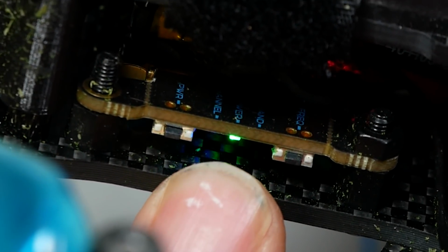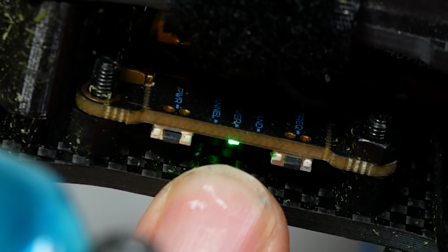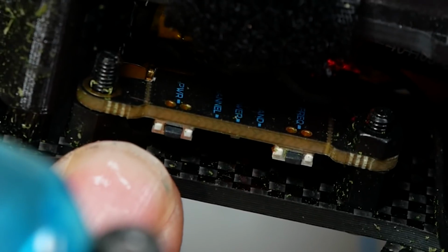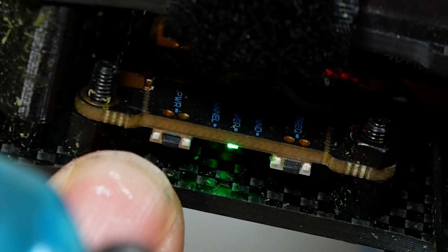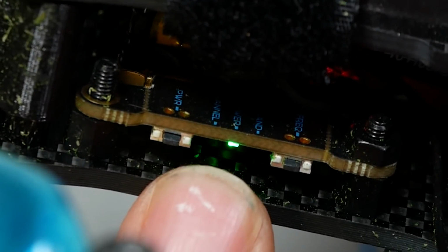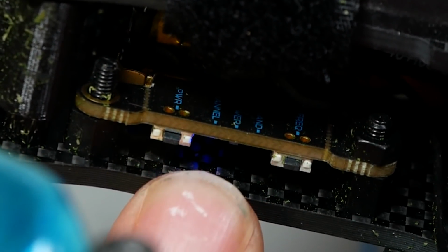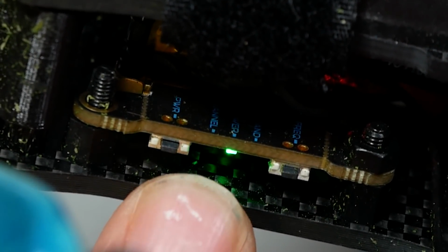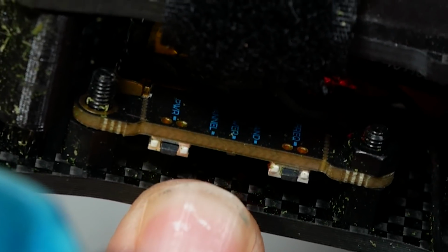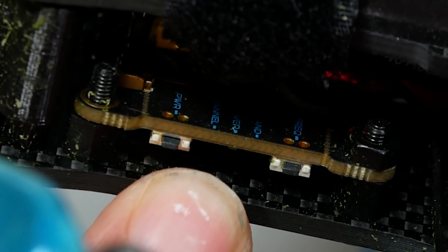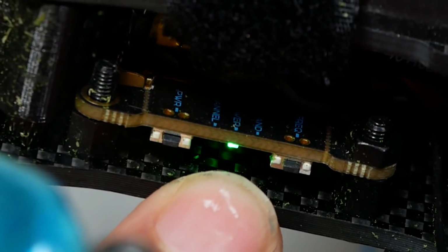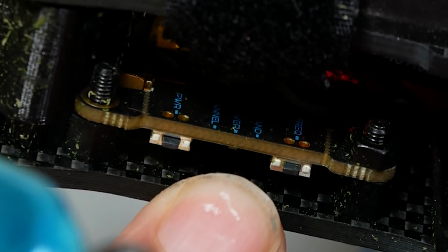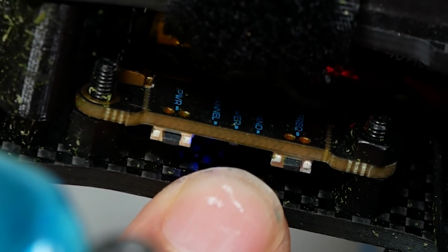And if it's blinking, that means the video transmitter is in what's called pit mode. And the idea is that if you are at a race and you are in the pits, like where they work on the quadcopters, and you want to test your video transmitter out, normally you would not power that video transmitter up at all because you could stomp on the signal of somebody else who is racing and cause them to crash out. Well, the idea behind pit mode is that the video transmitter will be in a very, very low power output. And that's why my video looked like crap. It's not at 25 milliwatts. It's at like 0.1 milliwatts.